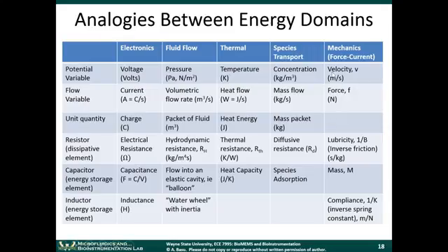The one that I'm going to talk about in this class, which in my opinion is more intuitive, is the force current model. It's less intuitive than the electronics, the fluid flow, and the thermal models, because when you're dealing with mechanics, you're not really thinking about something flowing from one place to another. If we think about this rigid body mechanics problem, we're thinking about just the movement of the mass, period. There's no flow of one thing to another. Okay? But it turns out you can model mechanics using circuits, and it's done all the time.